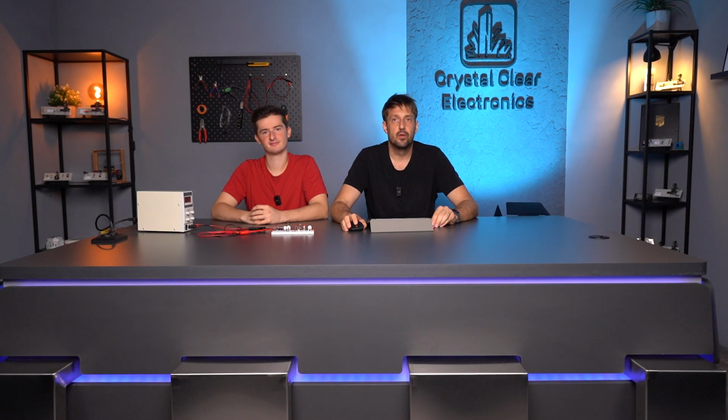This characteristic of the device makes it very useful wherever we need a constant voltage over a range of different currents. It is important that we connect Zener diodes backwards compared to regular diodes, so their cathode will be on a more positive potential compared to the anode, since this is how the Zener voltage drops. Zener diodes are often used as simple voltage stabilizers. They can be found in a wide variety of through-hole mounted and surface mounted forms.